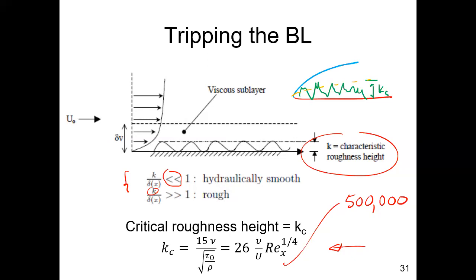And the reason for that has everything to do with molecular momentum exchange. In laminar flow, the ability for particles to move up and down and impart momentum is much less than in turbulent flow where the fluid's already moving in 3 dimensions. And so you don't need as much of a boundary layer to have the signal processed. What's the signal? Hey, at the flat plate, the velocity is 0. That's always the signal being processed. There's a boundary somewhere.